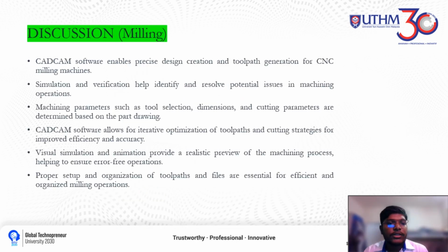And now the discussion for CNC milling. CAD/CAM software enables precise design creation and toolpath generation for CNC milling machines. Secondly, simulation and verification help identify and resolve potential issues in machining operations. Machining parameters such as tool selection, dimensions, and cutting parameters are determined based on the part drawing.